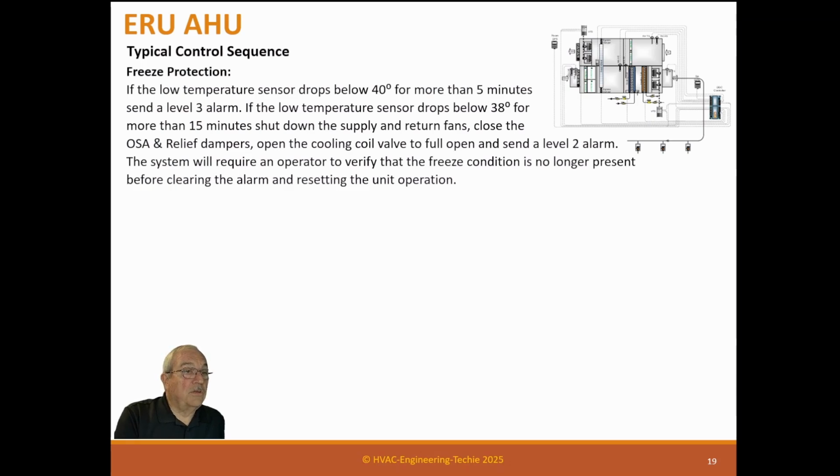Freeze protection. If the low temperature sensor drops below 40 degrees for more than 5 minutes, send a level 3 trouble alarm. If the low temperature sensor drops below 38 degrees for more than 15 minutes, shut down the supply fan and return fan, close the outside and relief dampers, open the cooling coil valve to full open, and send a level 2 trouble alarm.